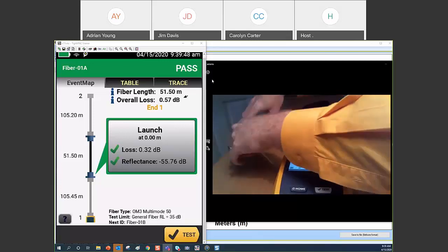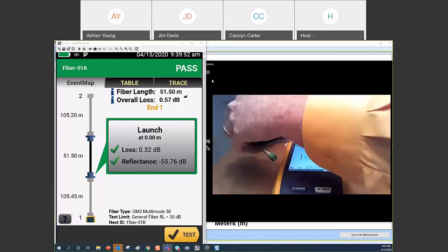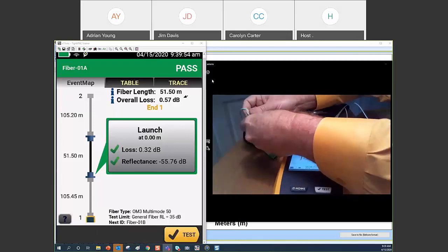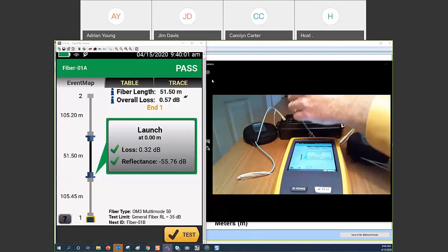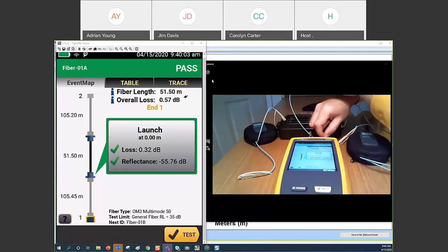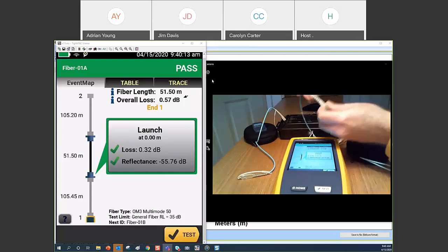And let me point out what I'm using here. This is actually a little bit interesting. I should have explained this before. What I've attached is something that we call a port protector. You might even refer to this colloquially as a sacrificial cord. Rather than plugging a lot into this, well, frankly, it's a little bit expensive. A high quality port on an OTDR costs money. We want to protect that. We'd rather sacrifice this cheap cord.